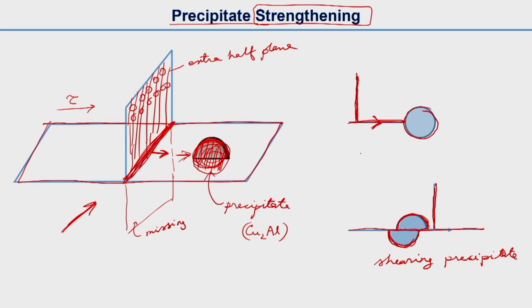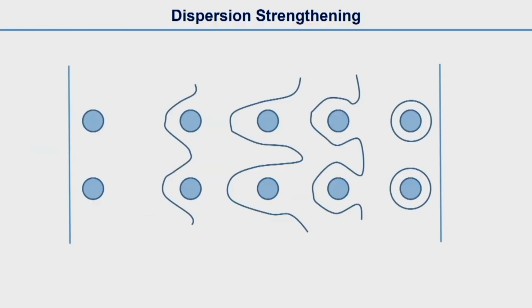But these are the precipitates which we call coherent precipitates. Coherent, please check what is coherent and incoherent. In very simple language, the coherent precipitates are easier for these dislocations to cross, but there can be some incoherent particles, and now we are coming to dispersion strengthening. These are some particles that can be incoherent. Probably I said inherent, that should be incoherent. These incoherent particles can be some inclusions, or some dispersed particles, or some can be incoherent precipitates.